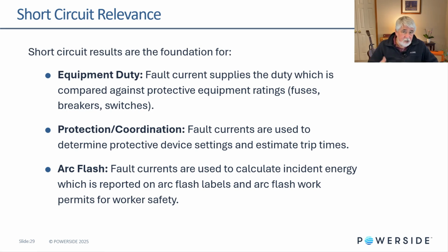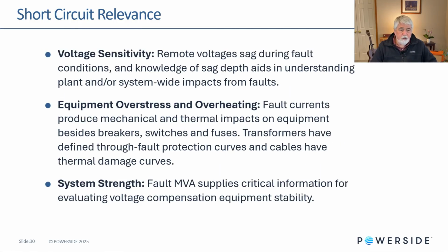Arc flash, as I just noted, the fault currents are used to calculate the incident energy, which is reported on arc flash labels and arc flash work permits for worker safety. So without the fault currents, you cannot perform arc flash computations.